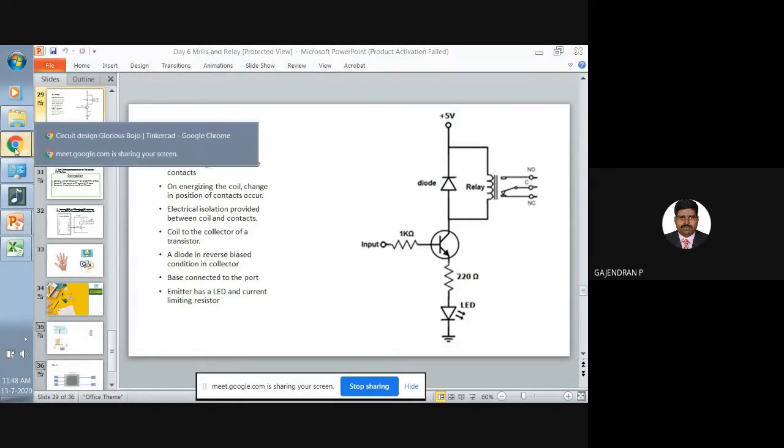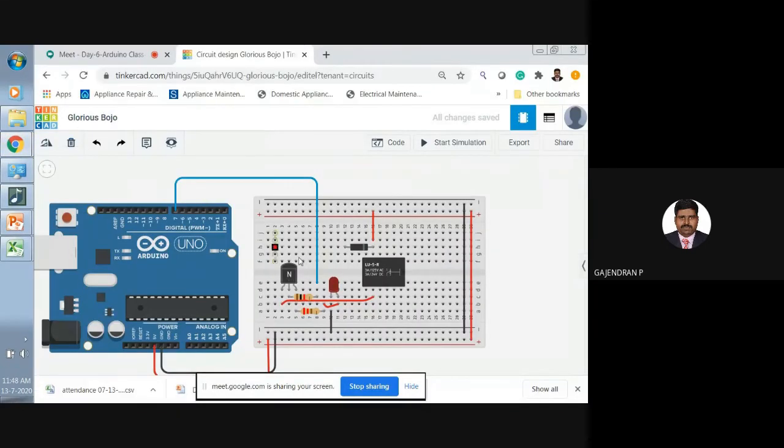Okay, so instead of going there, I can connect it here also. From here take one wire. That's all. So now I have connected the diode across my coil terminal. See, this is my coil terminal. This is one end of the coil terminal. This is the other end of the coil terminal.